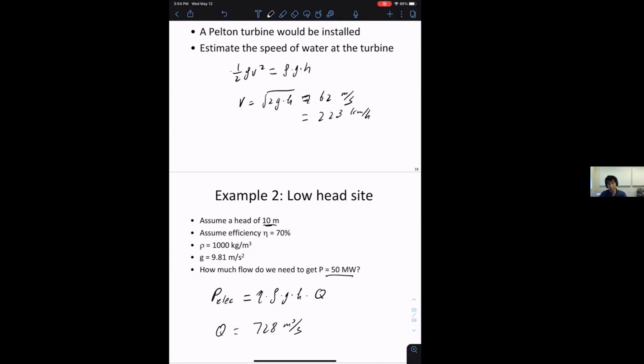So we say there's a finite amount of hydro resources. You often hear the sentence that the US has tapped out most of its hydro resources. It's because we basically run out of places where either H is large or H is small but Q is large. We don't have many of these places left in the US to build hydropower. So we've pretty much used all of them. But depending on which case we have, we use different turbines.